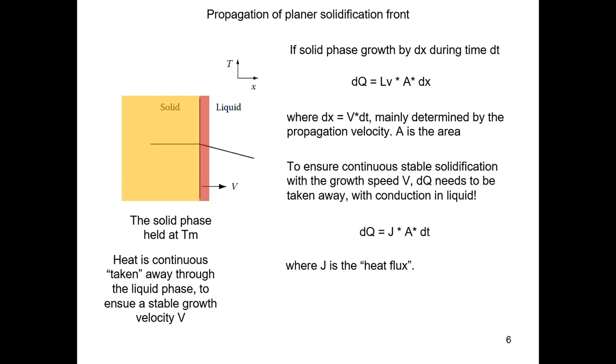In the case of hot melt, we'll use water as an example, but this might be a little bit confusing. In most cases, like in a real alloy or ceramic materials, or even polymer materials, the hot melt is very, very sticky. It's very viscous. So in those cases, the temperature gradient we impose is relatively small, because if you impose too large a temperature gradient, you're going to cause unstable growth very easily. We don't want that in this case.